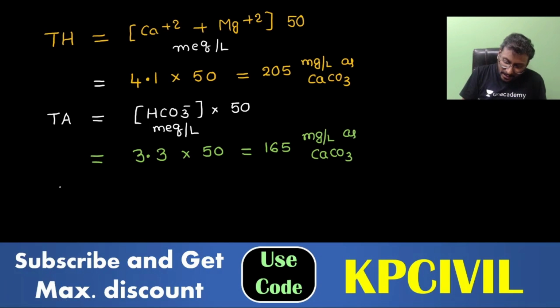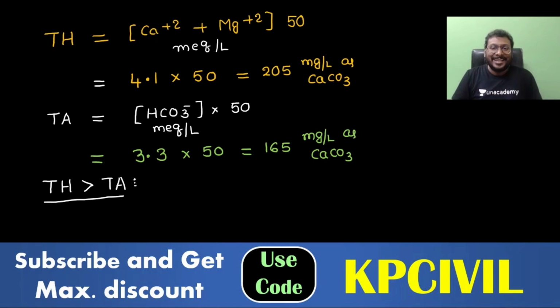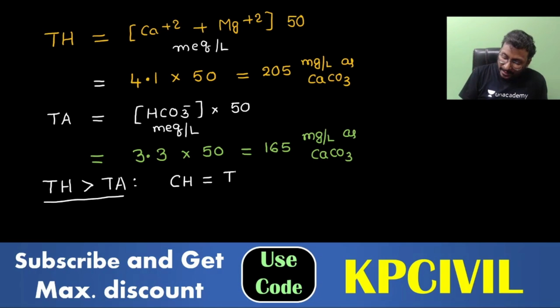Now what is the relation? TH greater than TA. So what happens if TH is greater than TA? Tell me what happened. CH is equal to TA. NCH, non-carbonate hardness, this is only required for us. Non-carbonate hardness is equal to TH minus TA.